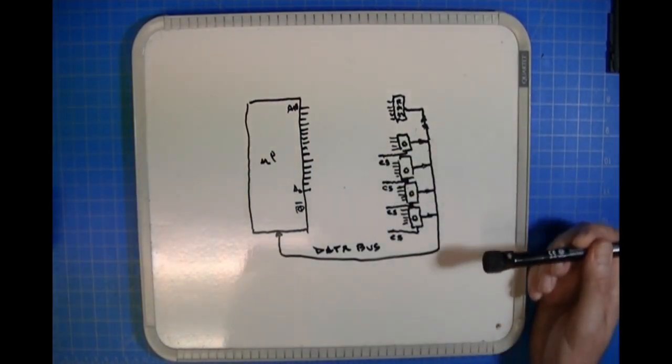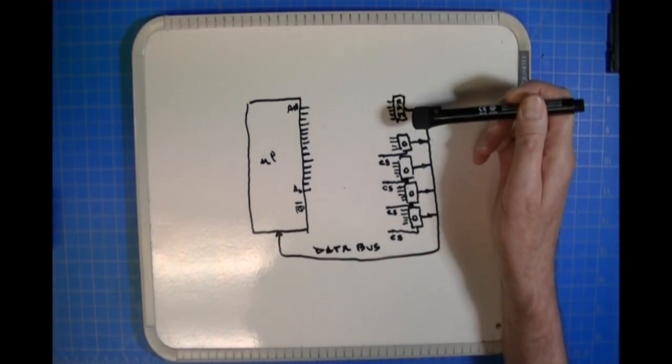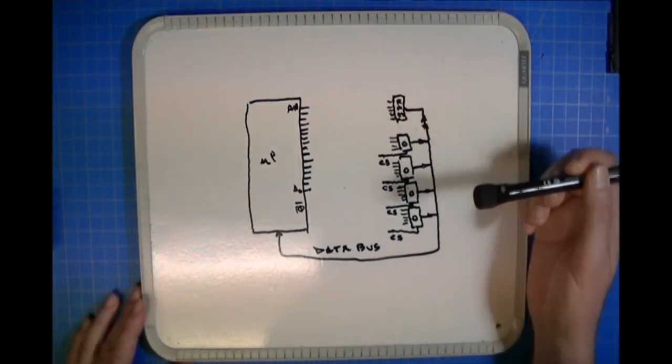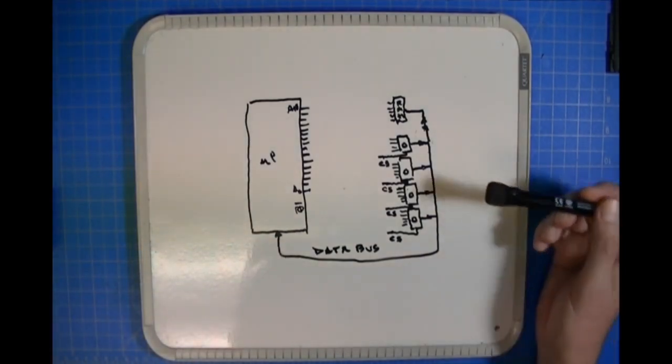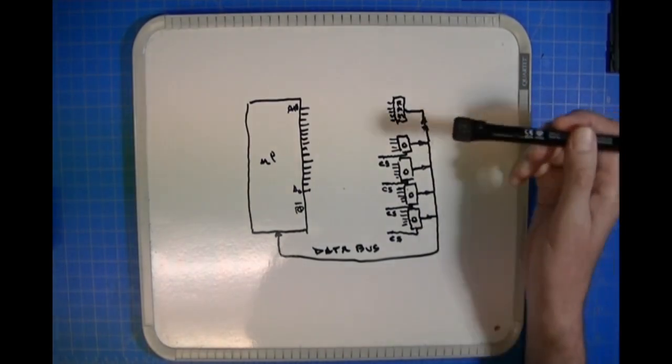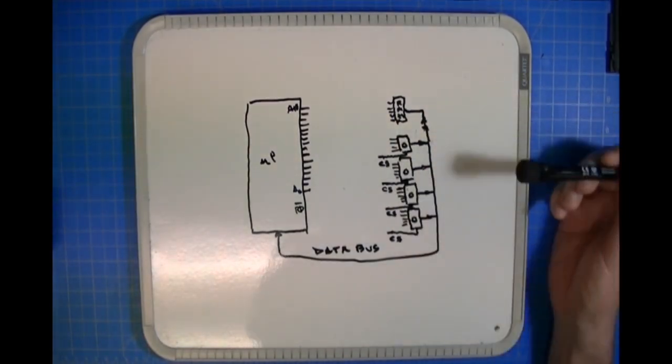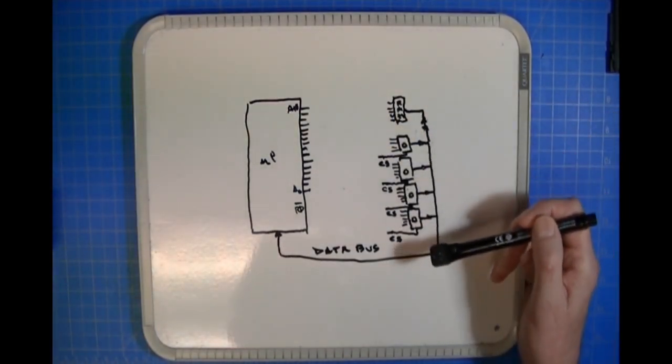These would be like 2716s. All right, and then up here we have a RAM chip, because microprocessors don't have any built-in RAM. RAM is where a software designer will store variables. He'll put a stack there and things like that. So you're going to have a RAM chip. RAM chips, when the power is removed, lose their contents. EPROMs do not lose their contents.